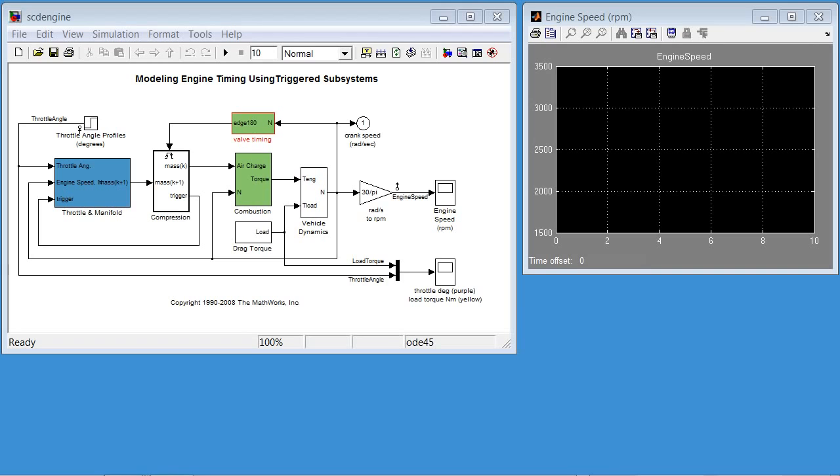This can happen when your Simulink model has such nonlinearities as triggered subsystems, like in this case, or pulse width modulation, or Stateflow diagrams. In those scenarios, you need to compute the frequency response of a Simulink model using simulation.